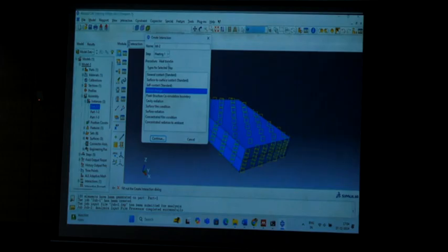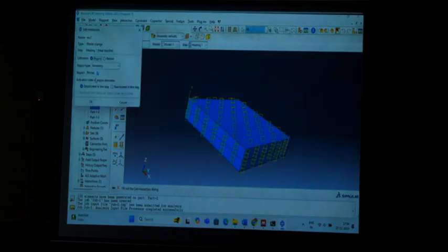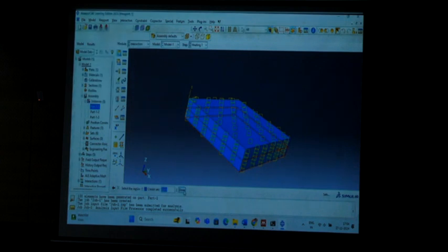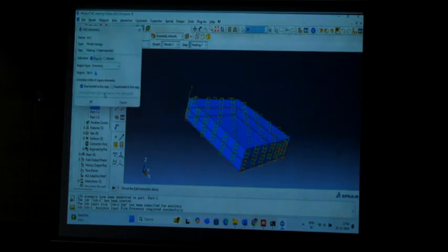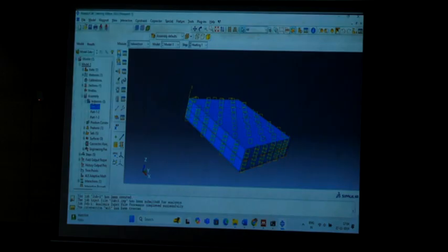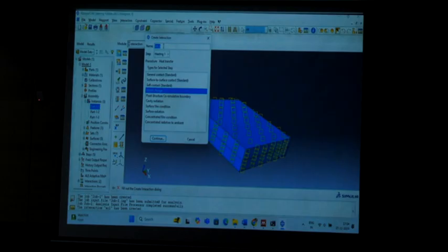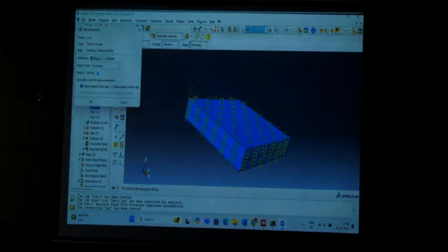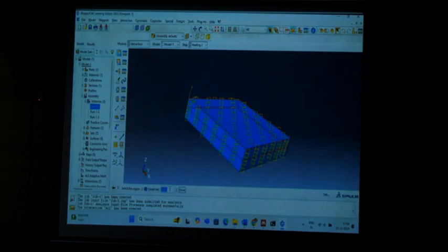Same thing, we have given it as MC1 model change. For the heating one, continue. It will ask you for the region option. I have chosen the bottom region, click on OK. We are deactivating in this step, and we will reactivate it further on. I will just click OK. In the same way you need to give the model change for the second heating too. MC2, continue. It will ask you the region, choose the option, done.